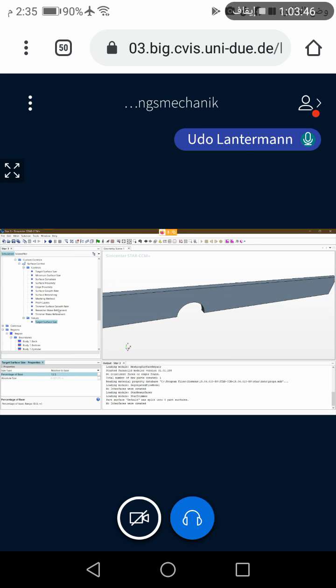And we also change the minimum surface size. Also, we don't want to use the parent value, so choose custom. And then we can set this minimum surface size. Default one is 10%, but we also choose here 12.5%. Okay, that's the first surface control.